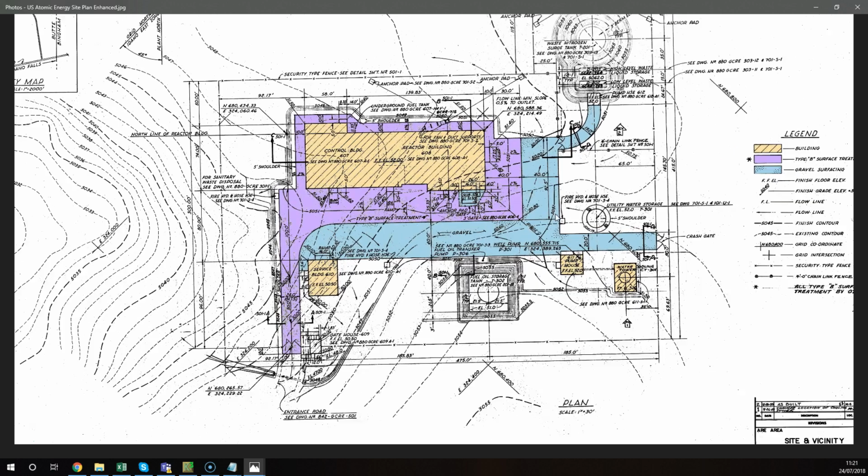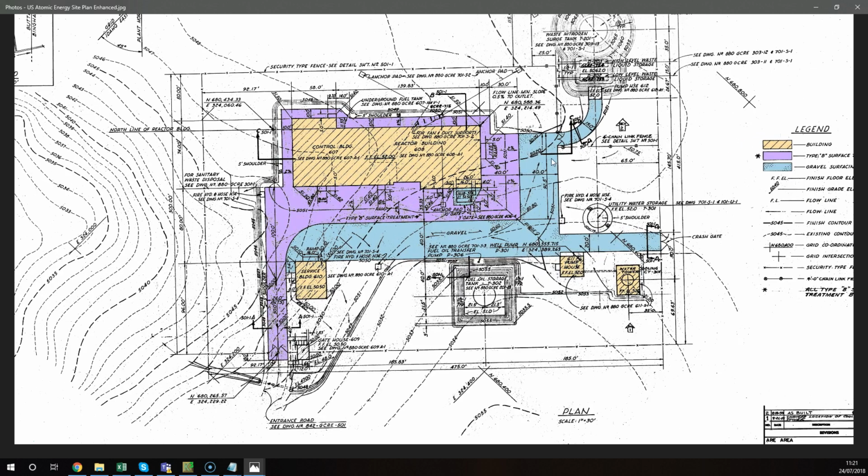Here it would be difficult to break the site up because the elevations aren't specified for different areas. There's elevations specified for the whole site, and we want to smoothly interpolate between those contours and then make adjustments from that. If we tried to break it up, we could end up with jagged edges because the different sections could not include the contour information that we need. So what we'd do in this case is try and take off all the proposed as a single feature surface and then make adjustments using the strip element. So this method is called the strip method.